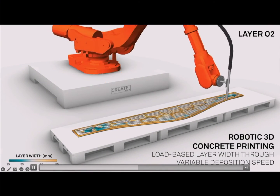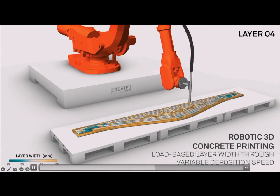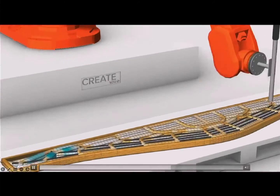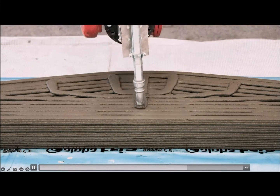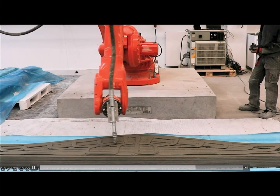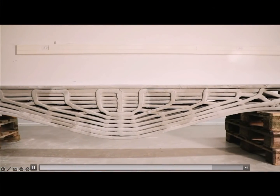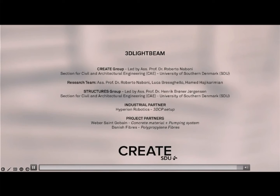And here you can see how our digital workflow went from designing the profile of the elements to selecting the stress lines and using those to create a toolpath, and then reaching the point where we fabricated. And this allowed us to avoid any moment where we had to discretize our geometry. So we didn't go through meshes, but we went directly from our curves, from our stress lines, to the toolpath and the fabrication process.